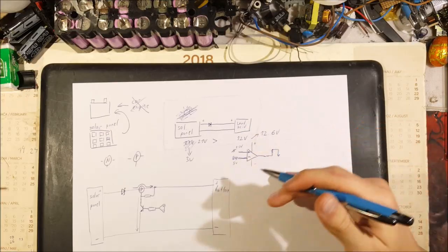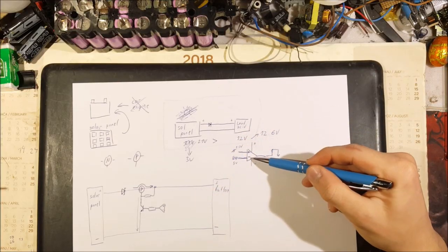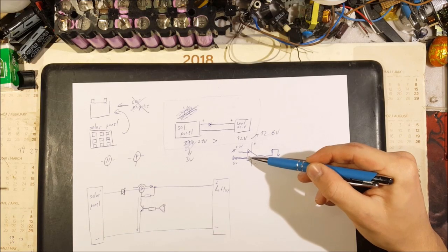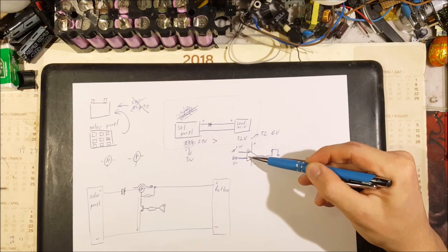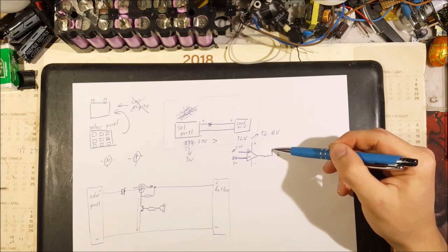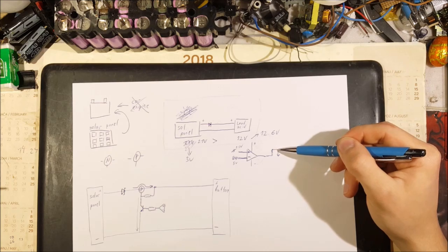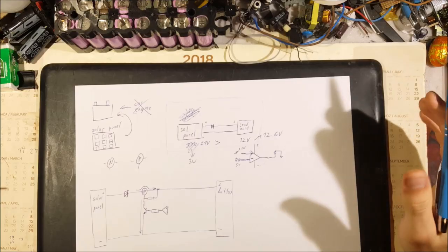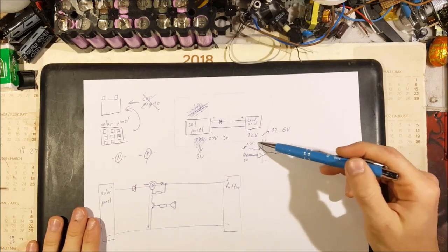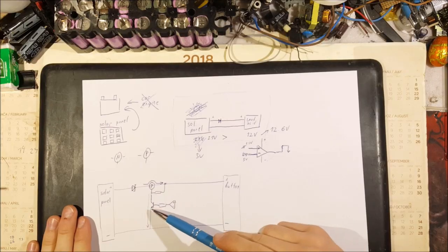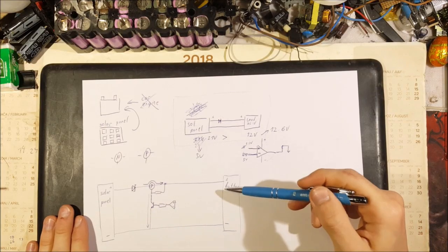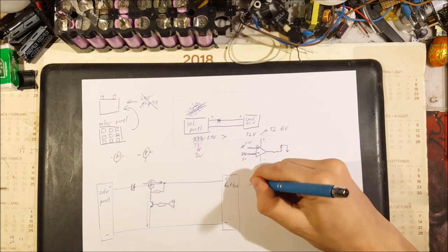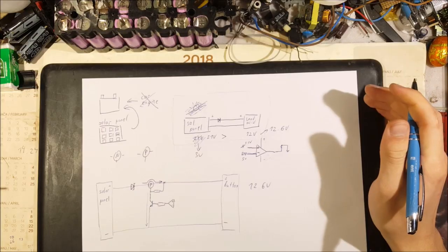So in a nutshell, how this chip operates is, as long as the voltage on the positive input is higher than the voltage on the negative input, the output will be pulled high, and if it isn't, the output of the chip will be pulled down low. We need to use this logic I showed here to control our little transistor to stop our battery from exceeding 12.6 volts.